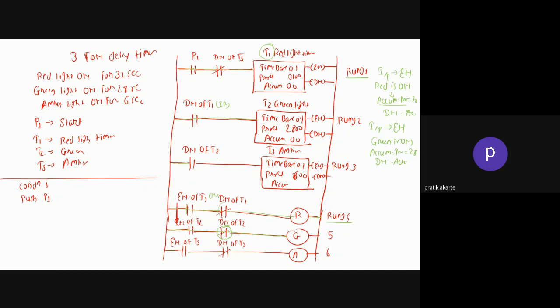So for the same internal relay we have two types of contact, one closed and one open. So you need not bother about which type of contact we are using, we are just sticking to our basics: once you get input, if there is a normally closed contact like this, it will get activated and the circuit is broken.